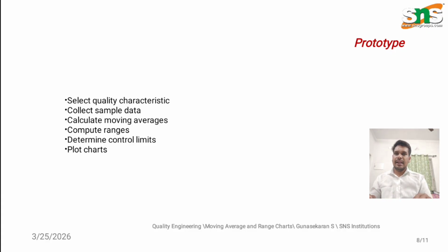Importance of range charts: it helps detect sudden spikes or drops in process variation. Even if the average is stable, high variation can affect product quality.